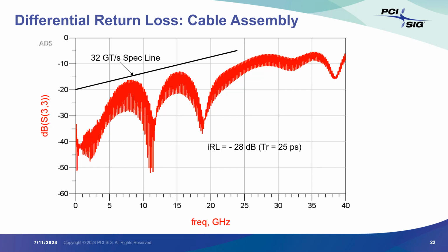So we can then make this IRL number up or down and scale the S parameters accordingly to see what is the impact if I keep changing the return loss characteristics of the cable. Of course, here we do it in a way that the S parameter still remains passive and causal, and insertion loss does not significantly change. So be careful with the application of such simplified metrics.